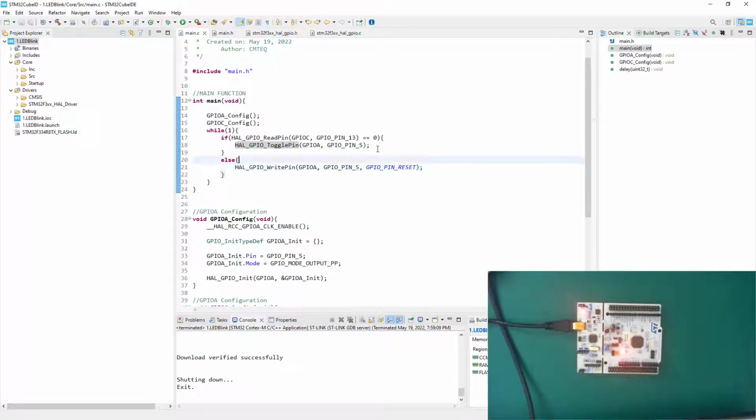Now for us to get this LED on, we need to put the pin state to 0. So that means I have to press here. You see? When I press, the LED comes on. I release, the LED goes off. Now mind you, when I'm pressing, I'm inside the if condition here. Because I'm pressing, I will stay there. I will run, but I will just be in there because it's true.